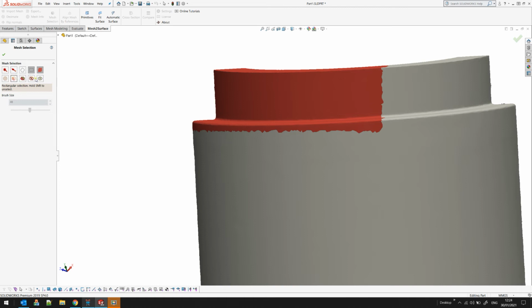The other buttons are dedicated for if you want to hide some of the triangles that are not needed at this stage. For example, imagine that this is a huge scan and only the area that I selected is of our interest. I probably want to work on something here and I don't need the rest. So these buttons will help me. The first button is called Isolate. What Isolate means is that it will take the selected area, leave these triangles visible, and hide everything else. I will just press the button so you can see.